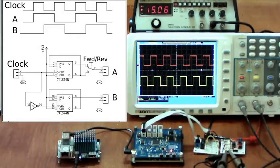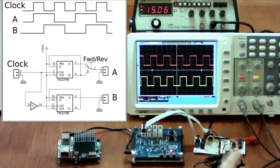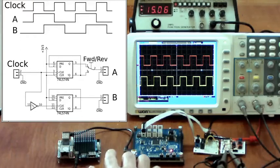Our test bed consists of a function generator, a circuit to convert the square wave from the function generator into the AB quadrature signals, a circuit to convert the 5 volts from the first circuit into 3.3 volts needed by the FPGA, and then a single board computer to run DP-Daemon and provide the API to our application. Let's rearrange the screen a little bit and open up two terminals so we can deal directly with DP-Daemon.